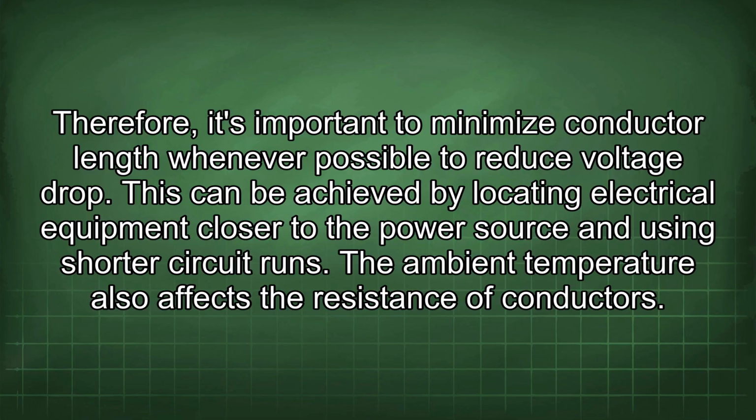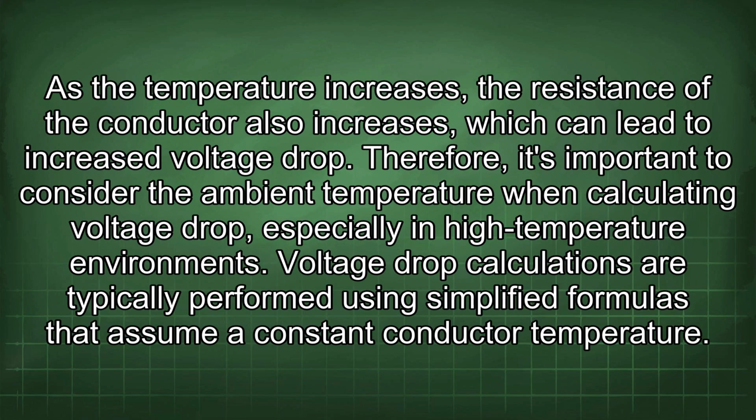The ambient temperature also affects the resistance of conductors. As the temperature increases, the resistance of the conductor also increases, which can lead to increased voltage drop. Therefore, it's important to consider the ambient temperature when calculating voltage drop, especially in high-temperature environments.